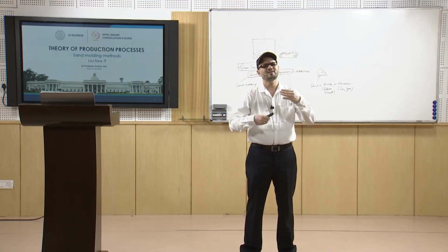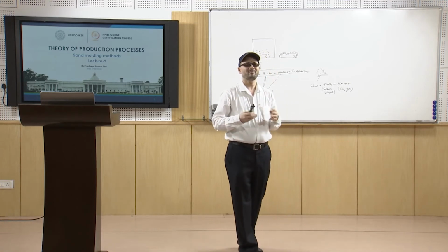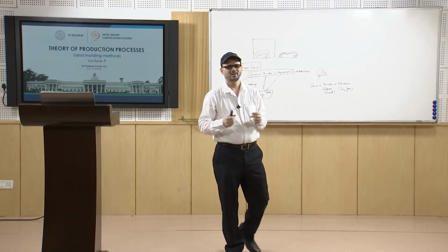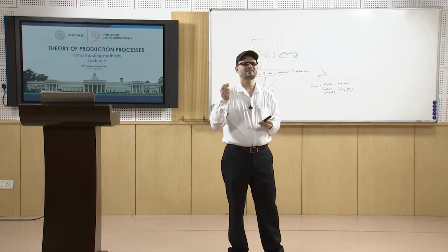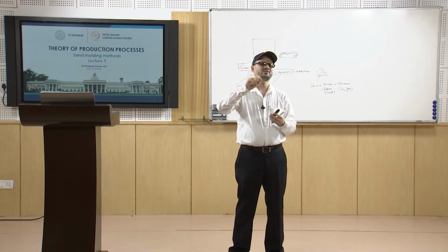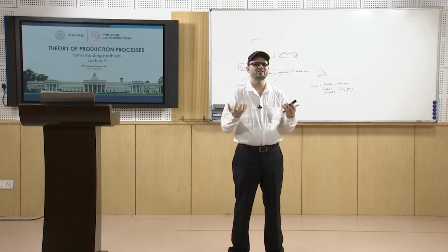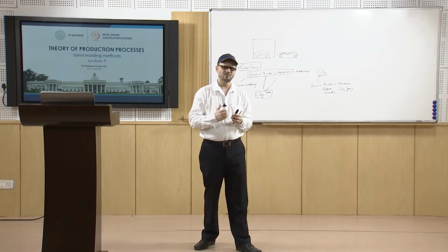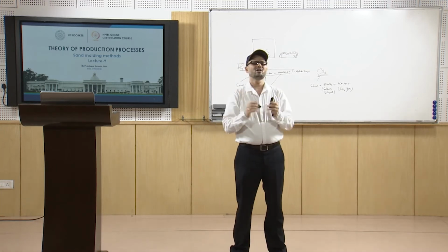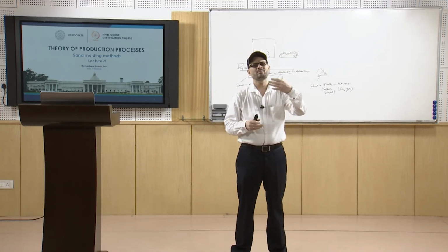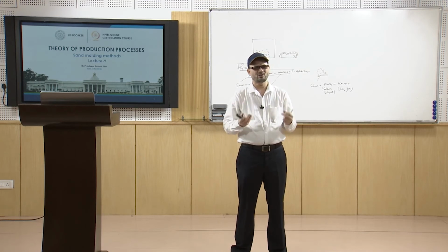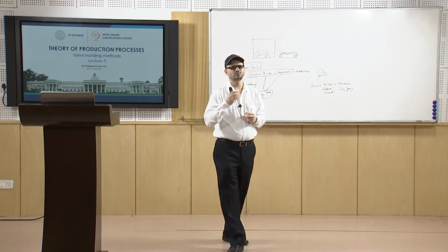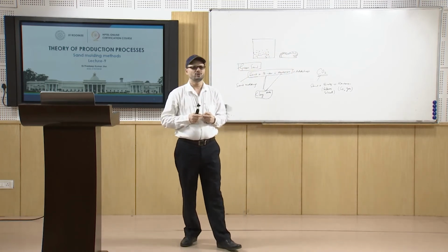So, that is one of the traits of plaster molding. Graphite is also used as mold. You can make the graphite mold from graphite and plastic beads, prepared by heating, or you can have graphite molds by machining a graphite column. Normally they are used when you have to use them many times, because graphite is costly, but because of its properties, for very precious types of castings, you use graphite molding also.